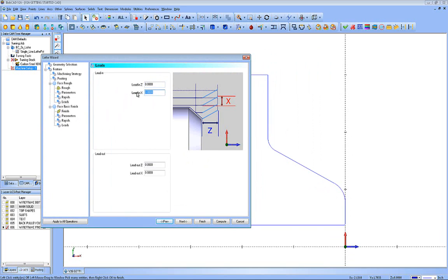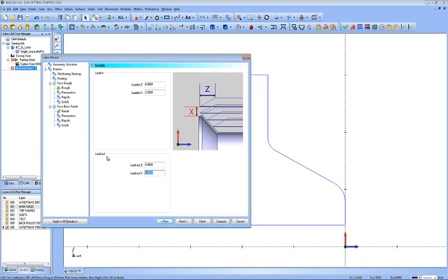So on the lead in and the X, I'm going to add 2.5 to it, the distance from this point up to clear my stock. Coming down from here to here is actually .375 in the minus direction, but I'm going to go minus 0.4. The reason why is the radius of the tool. If you were to stop right there, it would leave that little radius standing up right there, that if you want to cut that off, you need to actually come down past it a little bit.